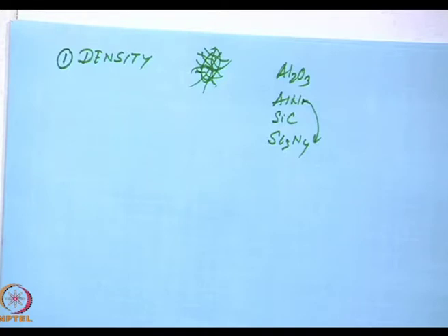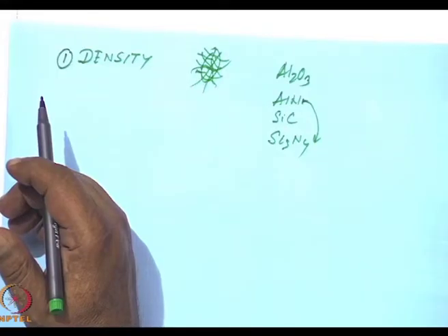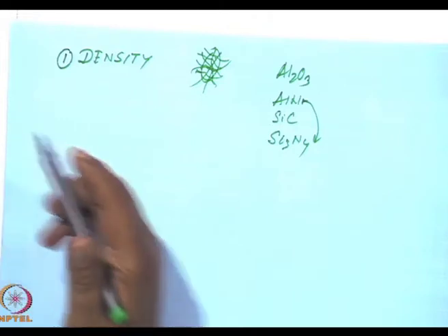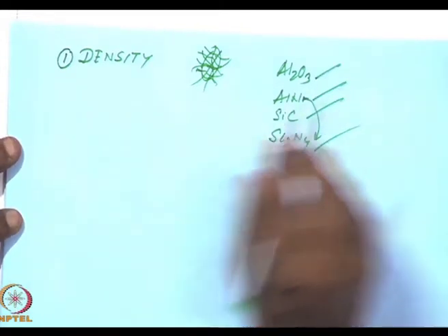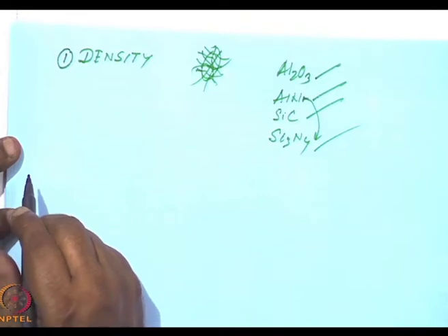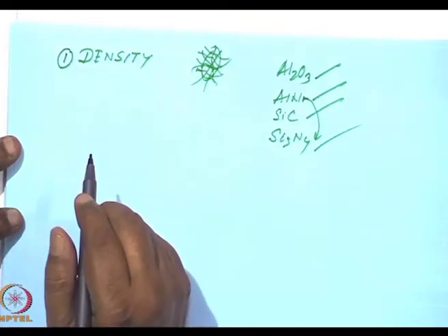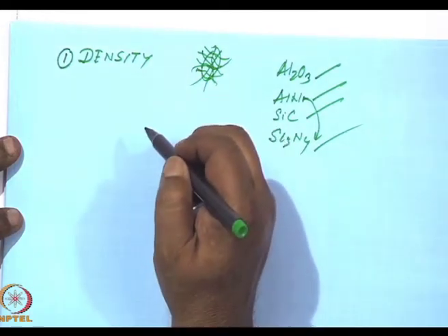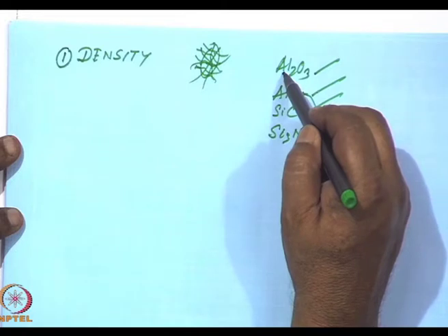I will have to know whether the aluminum nitride is porous. I have to know whether silicon nitride is porous, because I had told you earlier that porosity reduces sintering rates, because at times the sintering wave front gets blocked at the pores. So, how else to know it other than density, because densities of each product are very well known. If the material is porous, then the density of the material under consideration would be much lower than its mother product.